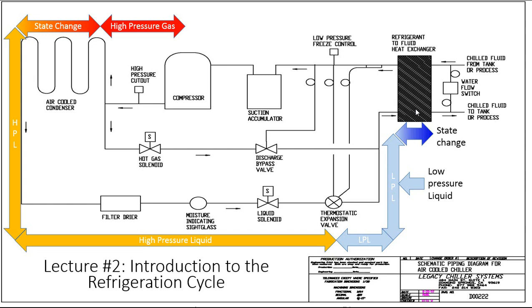They're using a refrigerant type gas as a propellant. When you press that button at the top, you're reducing the pressure in the can, creating a pressure drop, and that's causing the liquid in the can to start to boil. The surface of the can turns into a little evaporator. That's probably the easiest way to understand how it's actually working.